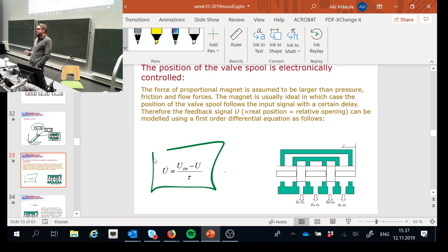That's telling where the spool position is, because it's a delay equation that tells you how the spool is having its value with respect to the control signal. So the components that I need in this equation are the signal coming from the joystick, then a feedback value telling how the current situation of the spool is, and then the third component is a time constant.